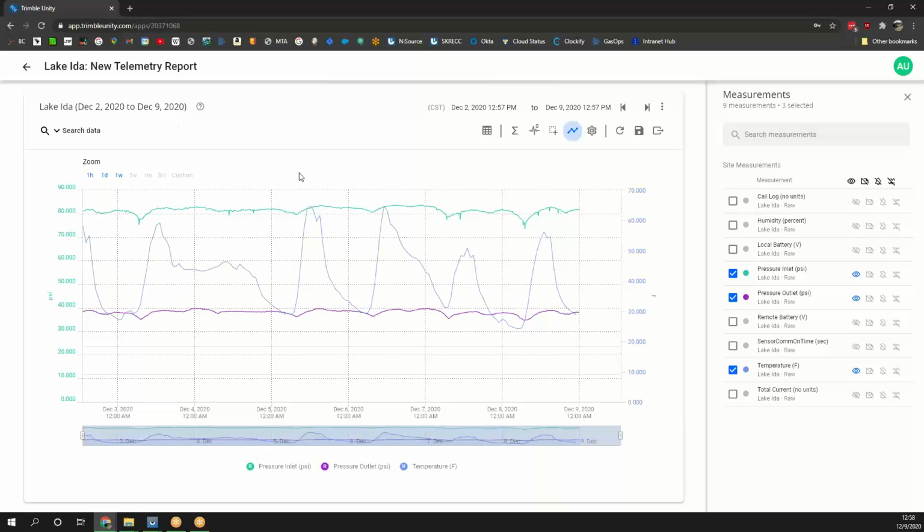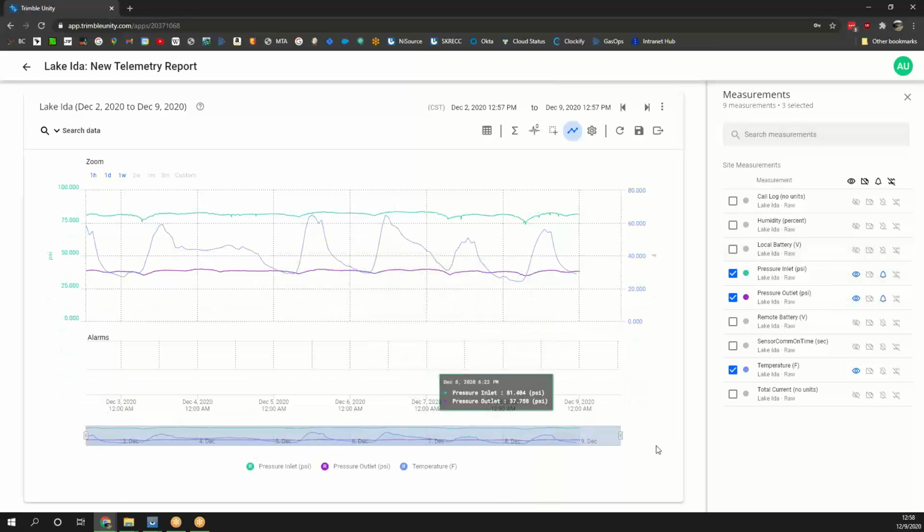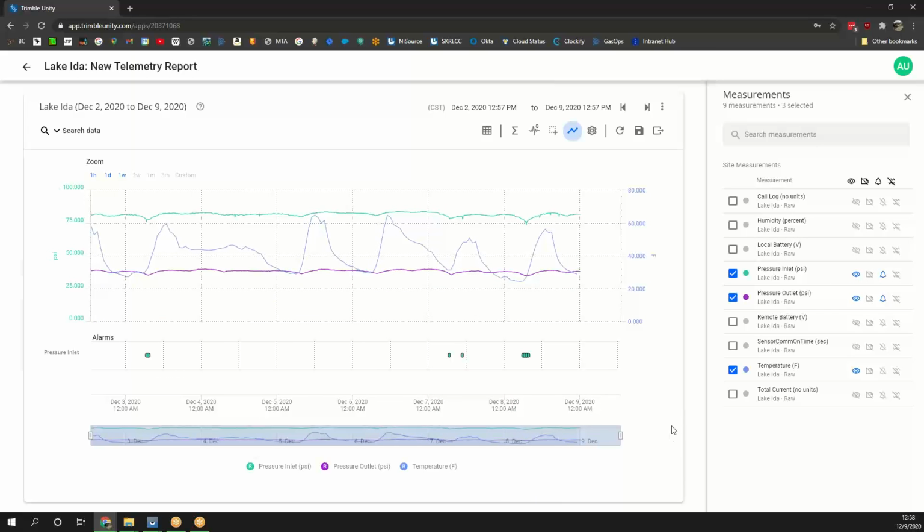And as those alarms hit, they will continue to send messages until the pressure rectifies itself or it's fixed by somebody doing something to it. And it'll also track the duration of that incident. Yeah, I forgot to mention that. Obviously, we can do notifications on these alarms. So email notifications or text message notifications let you know when these alarm values hit.